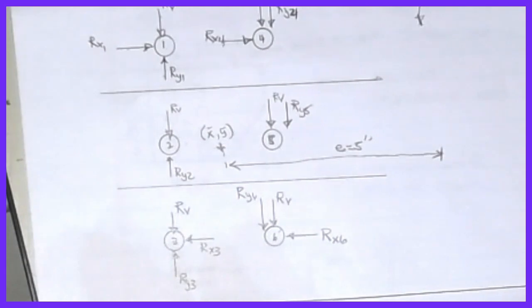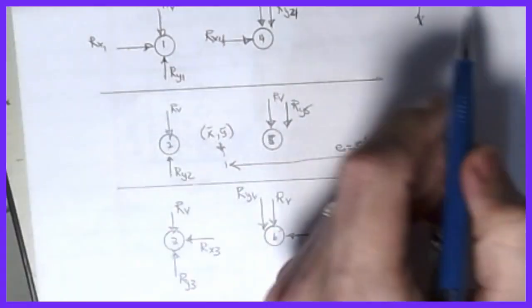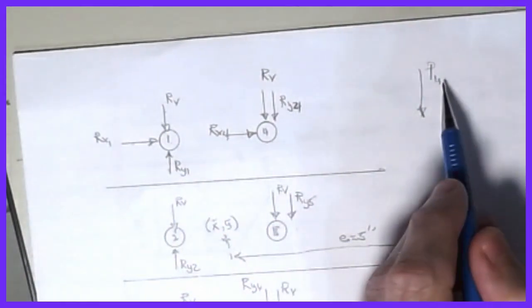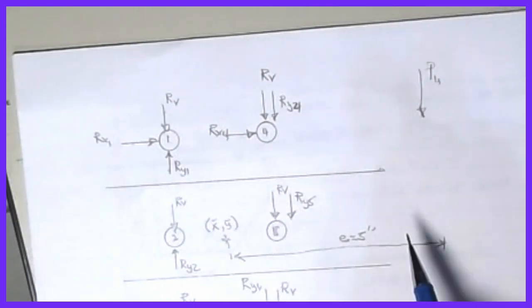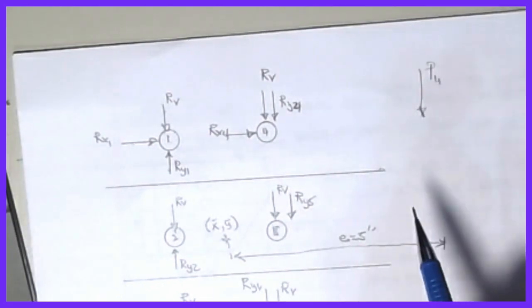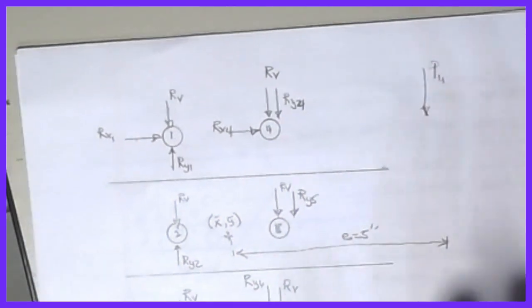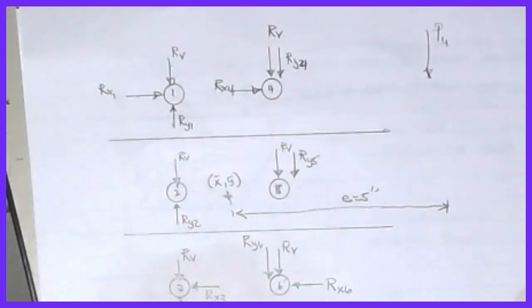So what we're after a lot of times is, maybe I know the bolt size and the location, what's the maximum load that I can put on this? It's almost like a load rating calculation. But when I do a design, I will do this at the end, when I start working on the arrangement of the bolts, to come up with the most compact, most efficient section, because this layout shouldn't ever control the design, structurally speaking.